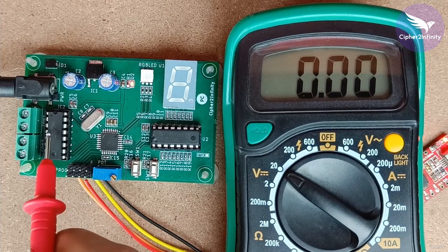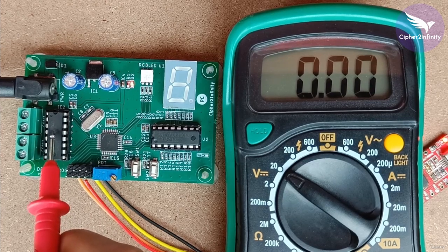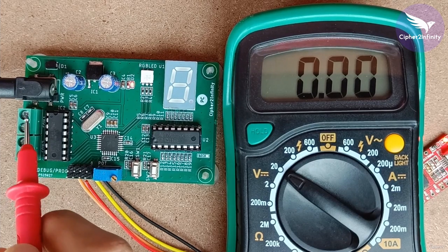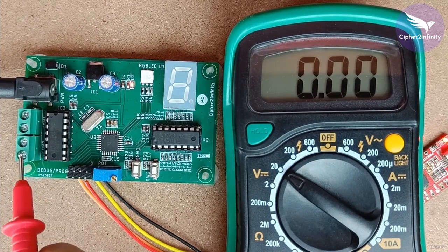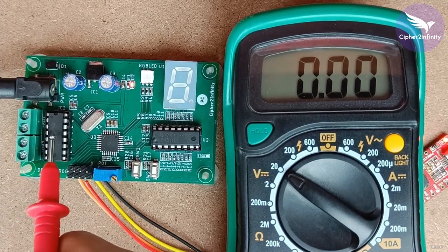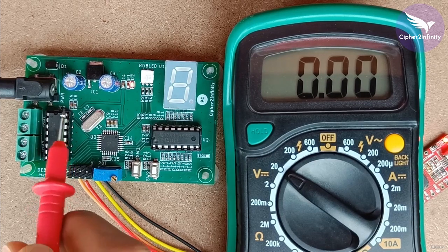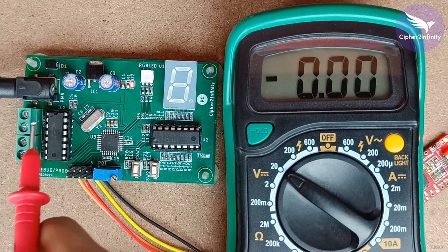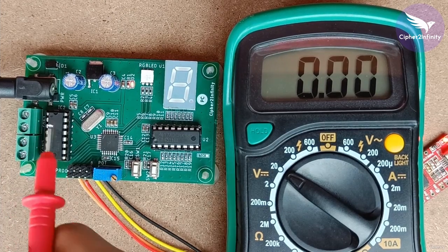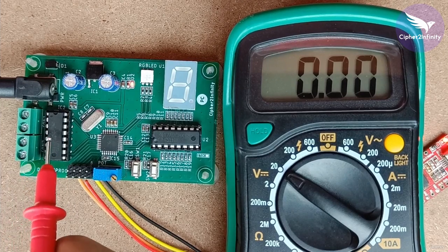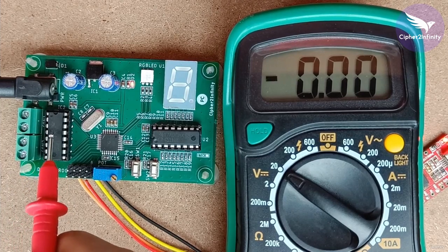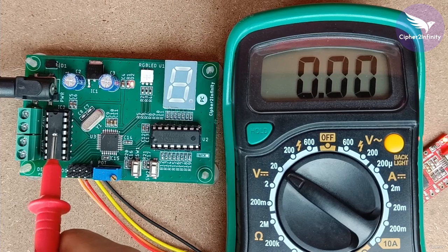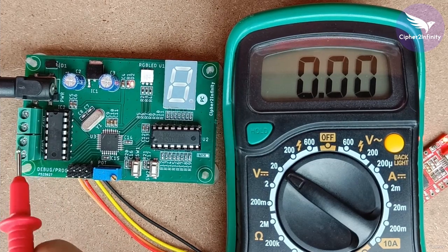After that, the second mistake that you can make is related to the motors. Before you connect the motors to these terminal blocks, you have to individually check whether the motors are working properly or not, because otherwise you will unnecessarily waste your time here, if the motors are not working even though your L293D section is working properly. In order to avoid such a situation, first check the motors, and later you can connect them to these terminal blocks.